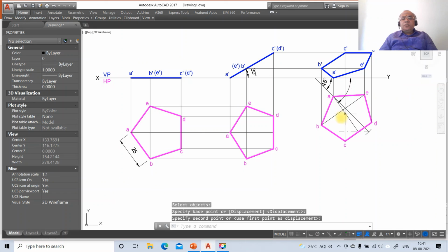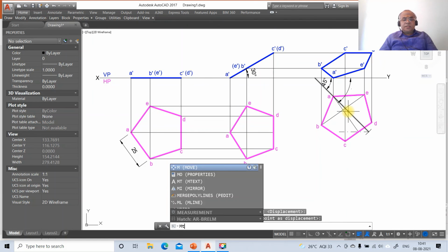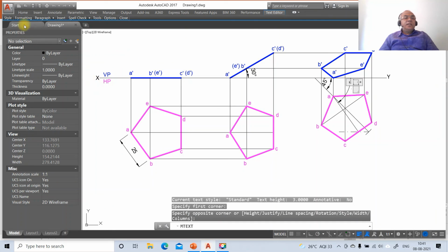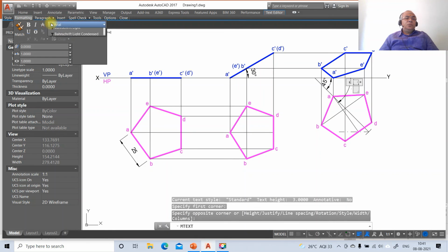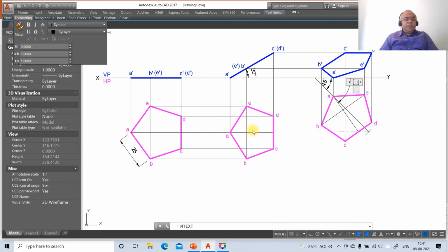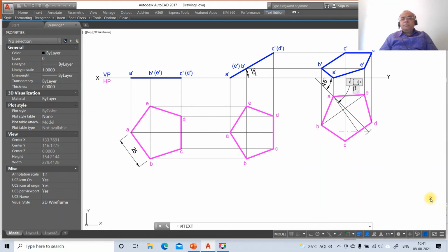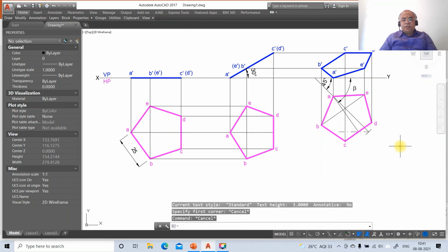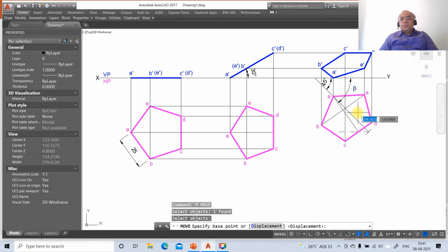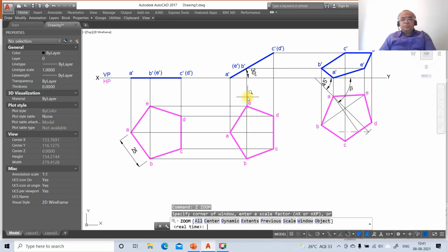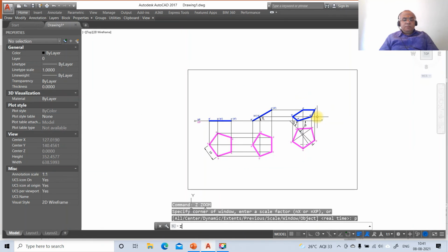And the one thing what I need is you just go to M-text. So M-text is to be written only after writing the text. So you just go to symbol. So select symbol and you mark it as beta B and small letter B. So it is going to give you the beta symbol. Then go to move, select this and place it wherever you want. So this is how you will be able to create this drawing by using AutoCAD.